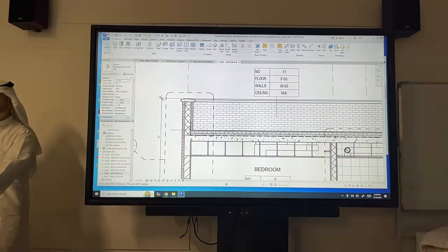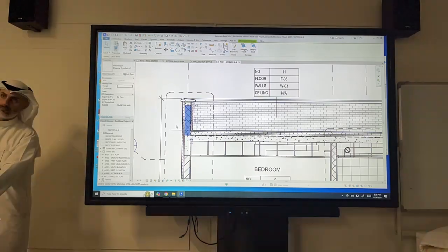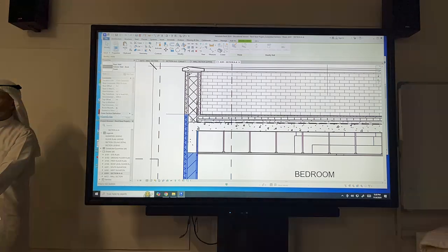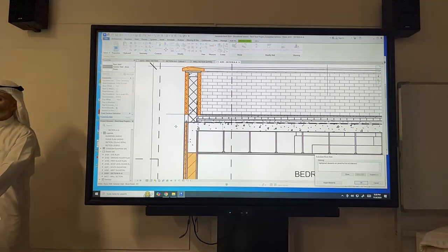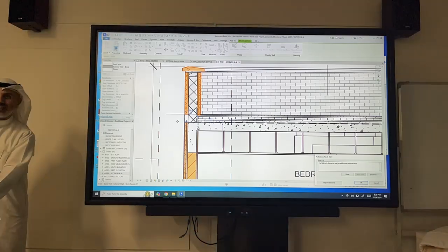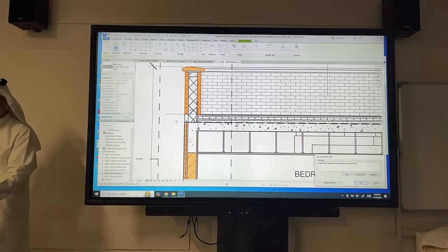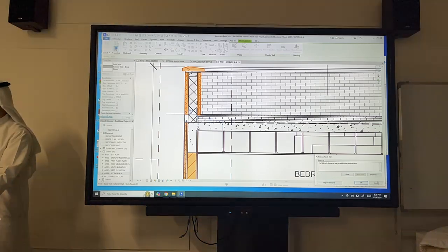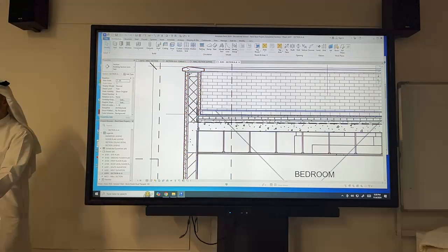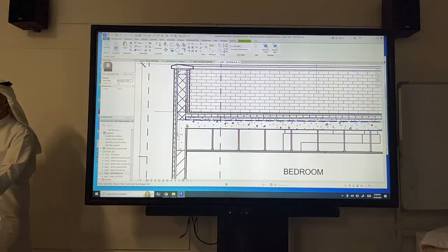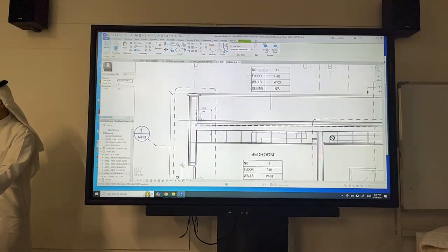Mask. Region. Region. Okay, just put a region on top, and if you decide to change the height and drag it to here, do you really want to deal with what's going to happen with that? And if you want elevations, it's going to be a disaster. Your plans are probably going to get messed up. So you have to join, unjoin elements. So just a region, and you're done with that part. Don't forget waterproofing membrane here.